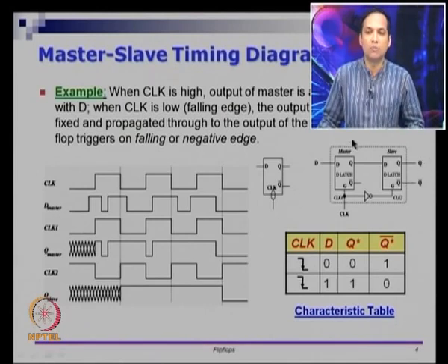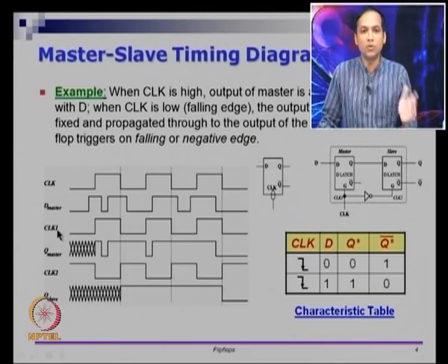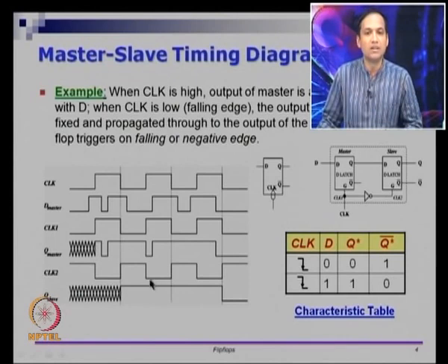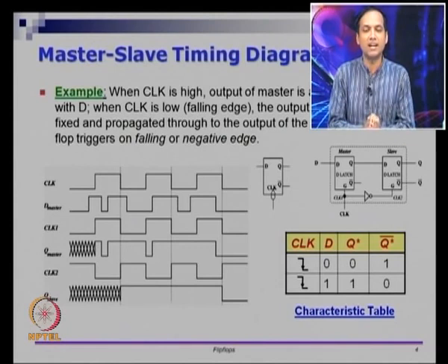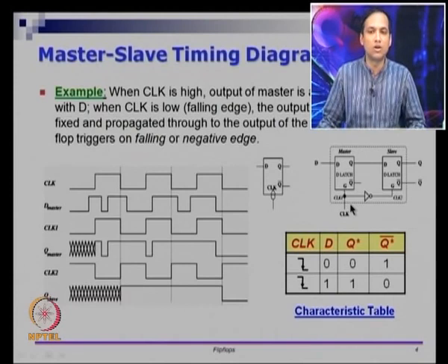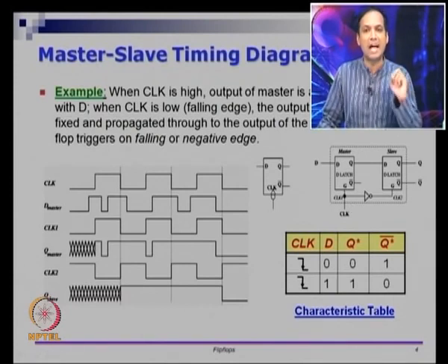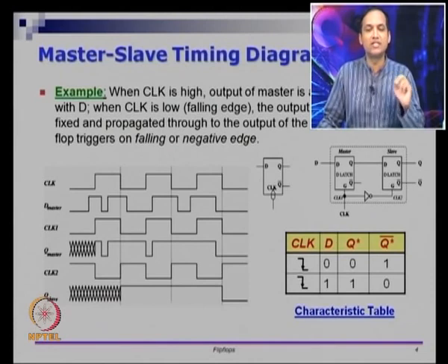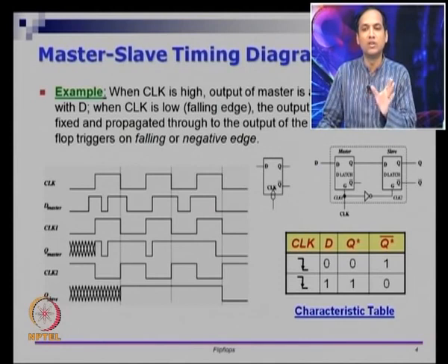If you look at the output of this whole circuit, the Q versus D relationship, Q has far fewer transitions than D. This is not the goal here, however; there is something else that has happened interestingly. I am now going to make a claim and we will verify that with the picture. The claim is that this overall black box, which I am going to call the D flip flop, is going to sample D only at the negative edges of the clock, and it is going to keep the value everywhere else.